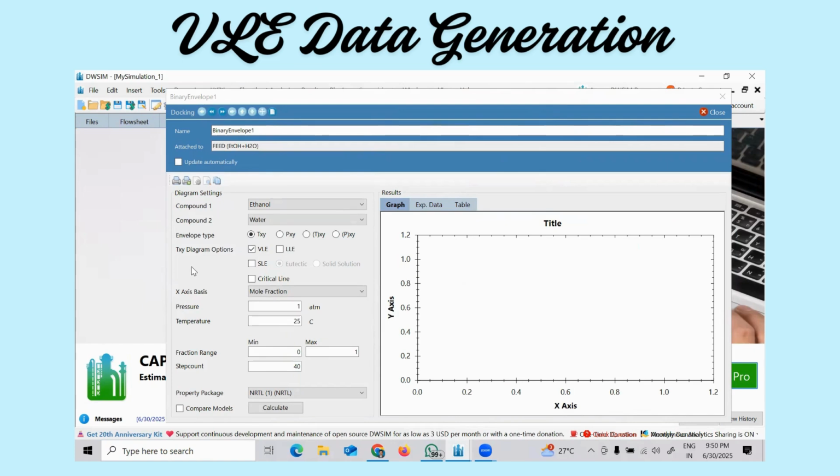Now what we do, ethanol water. Compound 1 is ethanol, which by default is a light key component, and compound 2 is the water, which is a heavy key component. And envelope type, we choose TXY by default. This is VLE, and x-axis basis is mole fraction, and the pressure is given, and temperature is given. All things are given here. There's a fraction change. The step count is very important.